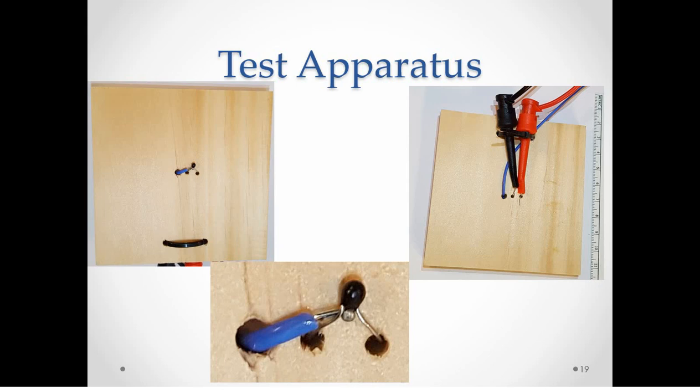5 small holes were drilled through the block of wood, 3 in the center and 2 close to one edge. From the front face of the wood block, the thermocouple with blue insulation was passed through the leftmost of the center holes. The silver bead that the blue arrow is pointing at is the point at which the 2 wires of different metals were welded together.